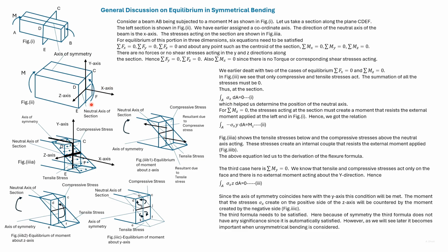There were no forces acting on this section along the x-axis, but there's a moment acting about the z-axis on this section. So while these stresses did not create a normal force, they will create a moment about the z-axis.